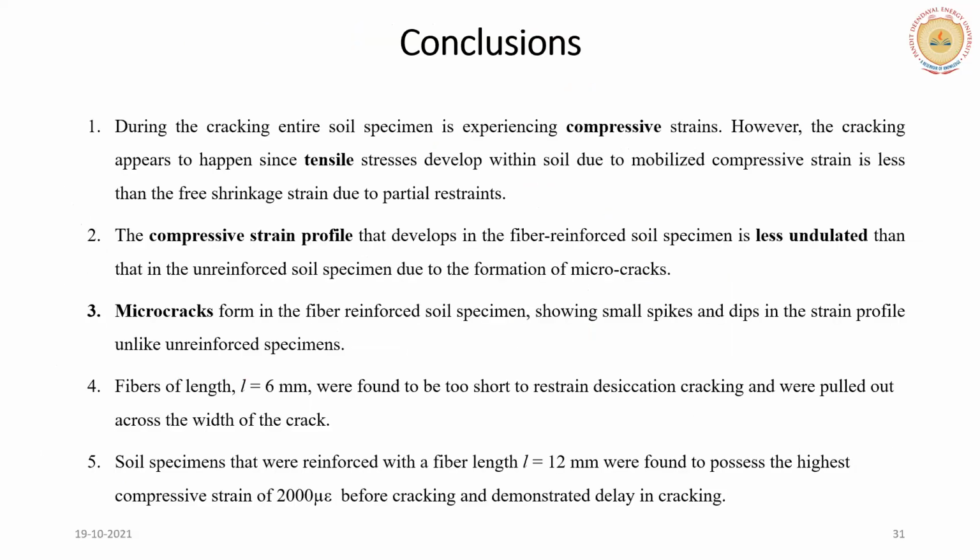So from this, during the cracking, the entire soil specimen experiences a compressive strain. First of all, we have to remember this thing. These compressive strains are actually causing the tensile stresses to develop, and they will cause the tensile crack formation.